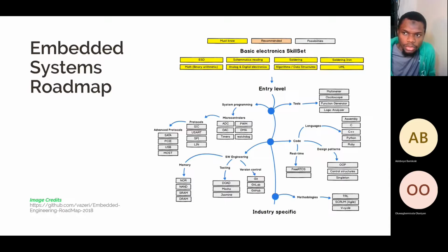You must know how to solder, you must know about analog and digital electronics, and you must know some binary arithmetic, like converting from hexadecimal to binary. Those are very basic fundamentals that are very important. You must know how to read schematics, understand the interconnection of components, and figure out what each part of the circuit is doing. And you must also know about ESD. ESD is electrostatic discharge. Have you heard about ESD before?